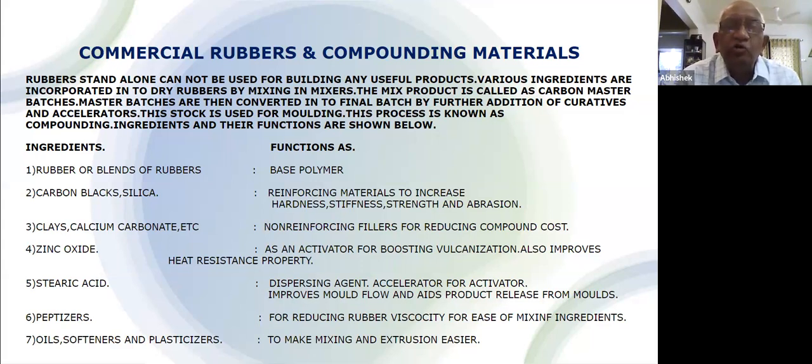In some industries, they use them for reducing the compound cost. But in some of the compounds, you cannot use the non-reinforcing filler because they will not be able to develop the required properties. Then there is zinc oxide, which acts as an activator for boosting the vulcanization process or curing process. It also improves heat resistance property.